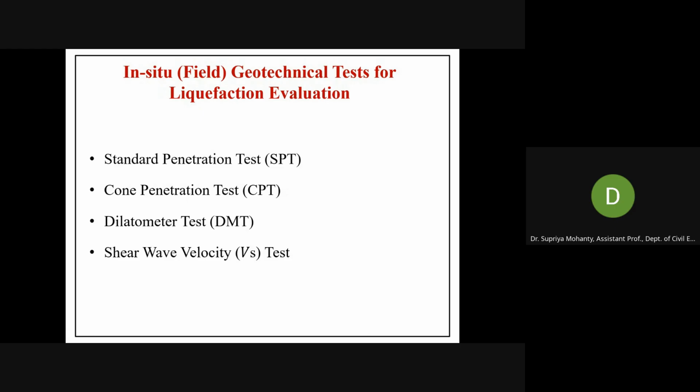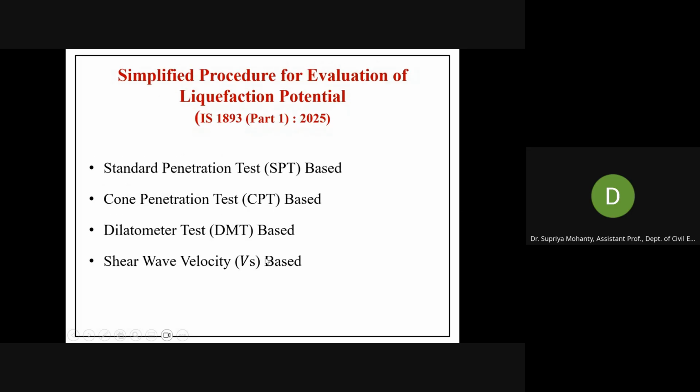And for liquefaction potential, particularly SPT, CPT, DMT, and VS are recommended. And the procedure based on these SPT, CPT, DMT, and VS is mentioned in our IS 1893, Part 1, 2025.